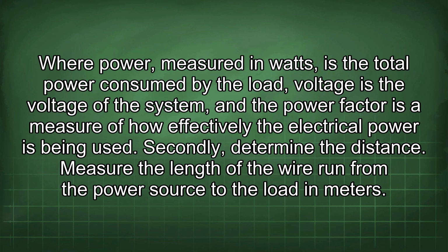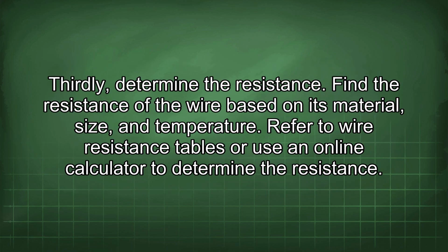Secondly, determine the distance. Measure the length of the wire run from the power source to the load in meters. Thirdly, determine the resistance. Find the resistance of the wire based on its material, size, and temperature. Refer to wire resistance tables or use an online calculator to determine the resistance.